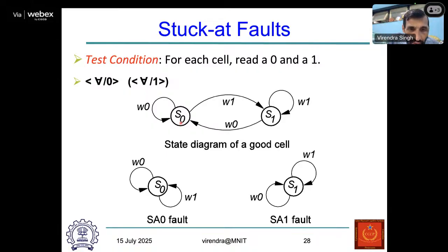At least I can say that this machine did not have stuck at 0 fault. No, sorry, stuck at 1 fault, because it is able to store the 0 value. So it is not stuck at 1. I can rule out that possibility if I can read the value 0.